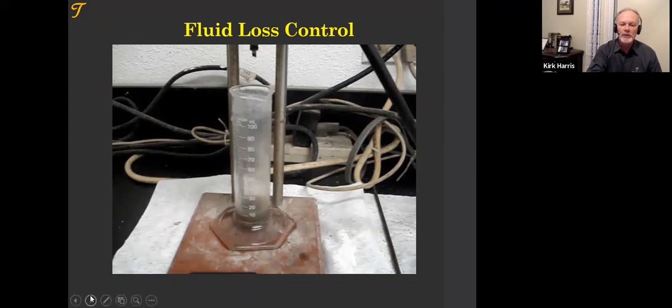We'll talk a lot in a couple of weeks about how much fluid loss you need, but we test it very simply. I would ask this question: why do we use a 325 mesh screen? When I was in research, I used to have cores of the actual formation, and we didn't lose that much fluid out of the cements going through 2,000 millidarcy or 100 millidarcy cores.